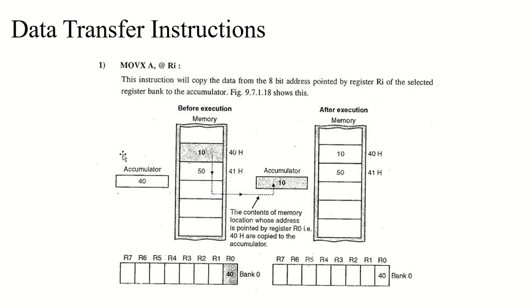In the second type, the data pointer is used for generating a 16-bit address, which is done for a larger RAM array, and port 2 outputs the high order address bits, which would be the content of DPH, while port 0 outputs the lower address bits, the content of DPL. DPH and DPL are the data pointer higher order address and data pointer lower order address, multiplexed with the data.